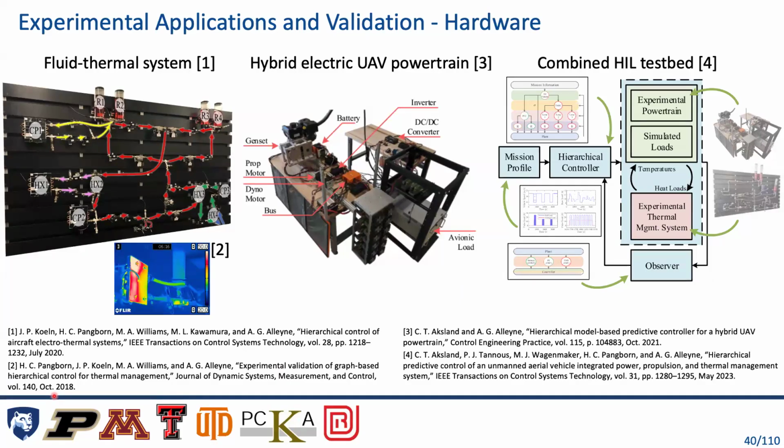But it turns out that we can develop a very accurate dynamic model with just two states. And that's what Chris mentioned. One state corresponding to the temperature of the fluid inside the cold plate, and one state corresponding to the metal of the cold plate. And these are averages because everything is distributed throughout the physical part of this component. But that's one of the enabling things here, is that if you just want a control-oriented model, you can get away with far fewer states than you might expect.